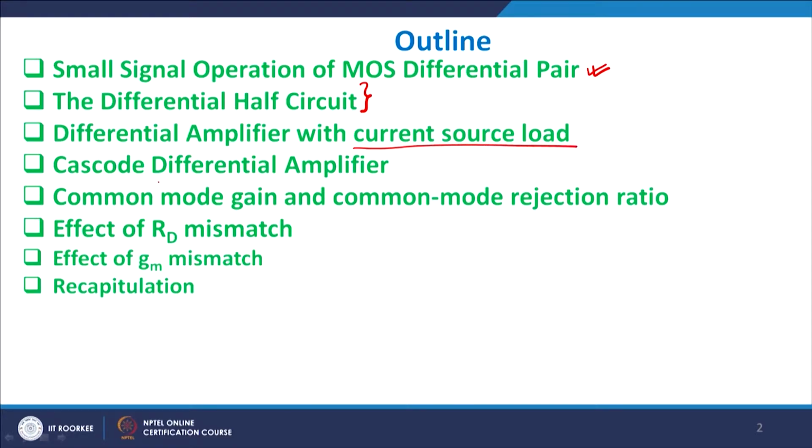Then we will look at the cascaded differential amplifier, and the meaning of CMRR with respect to CMOS technology. Till now we were assuming that the resistances in the left and right arm of a differential amplifier are exactly symmetrical, which means that both transistors have the same value of beta, alpha, and also the same value of the drain resistance RD.